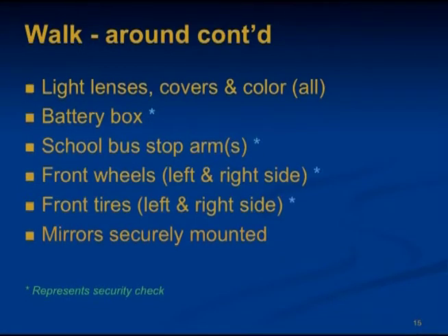Replace if necessary. Check the battery box, which may be located in different areas on different buses. Make sure the battery is secure, connections are tight, and the cell caps are present. Battery connections should not show signs of excessive corrosion. Make sure that the door locks, that there are no protruding wires or unusual items found in the battery box.